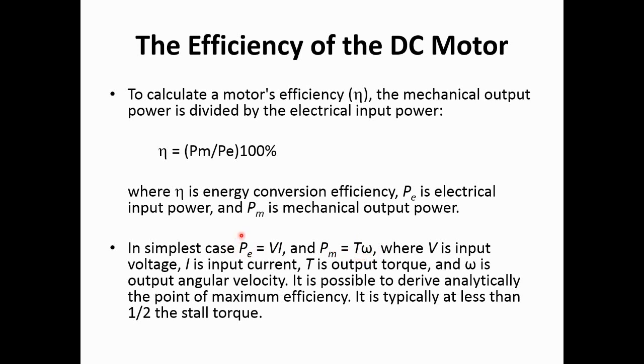And what about the electrical input? So, power output over power input, power mechanical over power electrical. Power electrical is simply the voltage multiplied by the current, right? So that's how we calculate the efficiency of a motor, right?